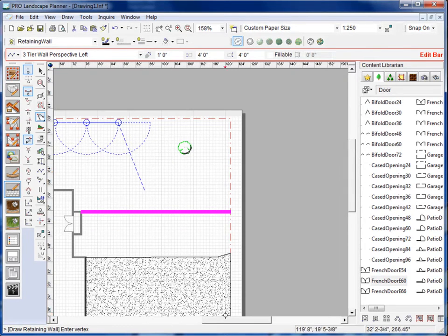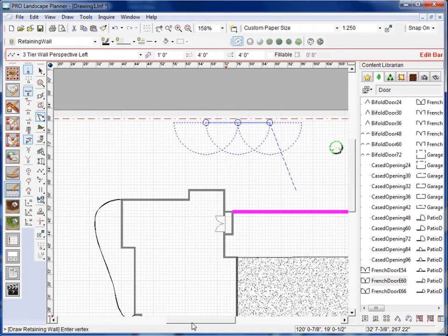Now the next snap tool is the intersection snap. The intersection is similar to the endpoint snap. When I select the intersection snap and a drawing tool, you'll see that the intersection is anywhere a line turns, just like all these endpoints are intersection points.